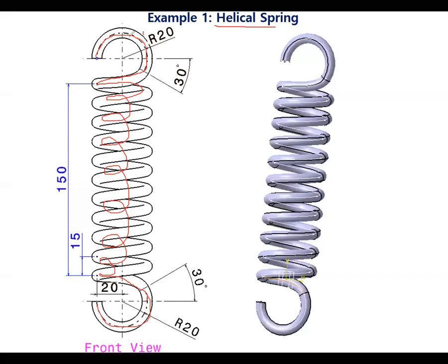After creating this connect curve, the helix and all three sketches, finally we will give a cross section for that helix. We can use volume sweep in generative shape design, or you can also go to part design and consider rib to give the cross section for that helix.